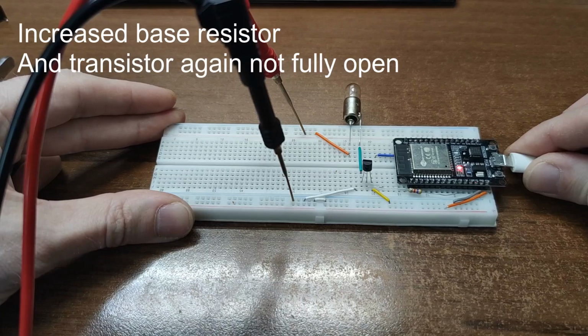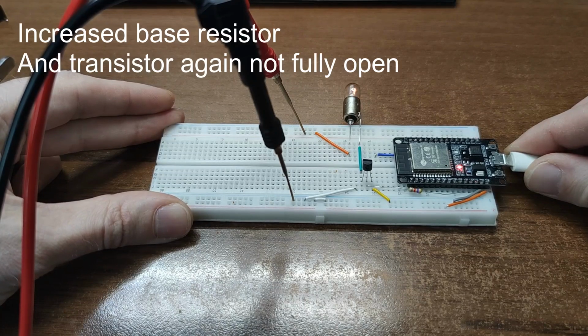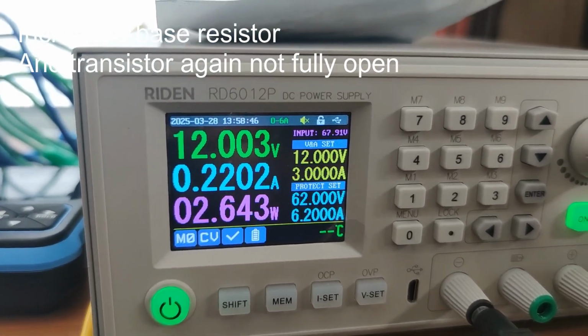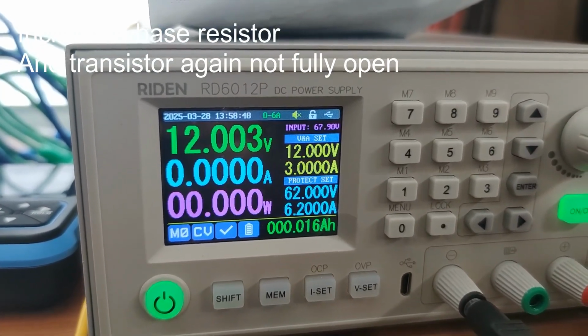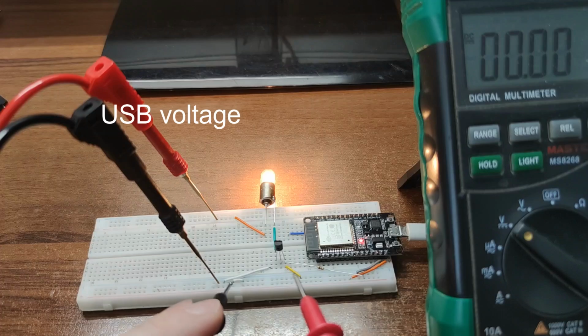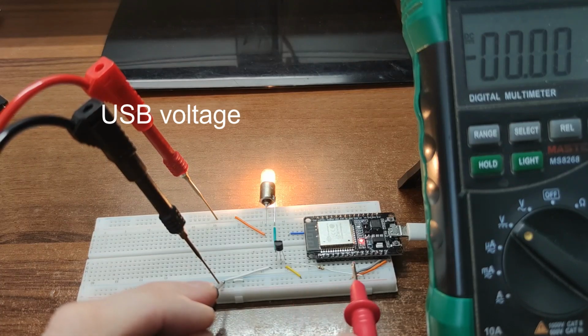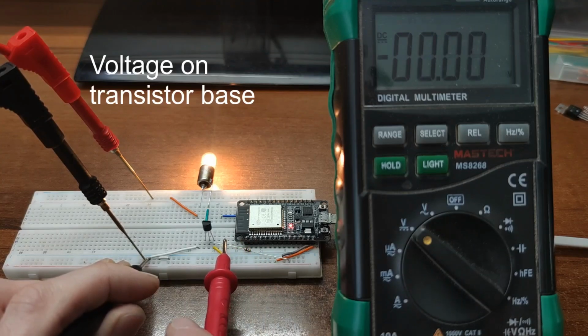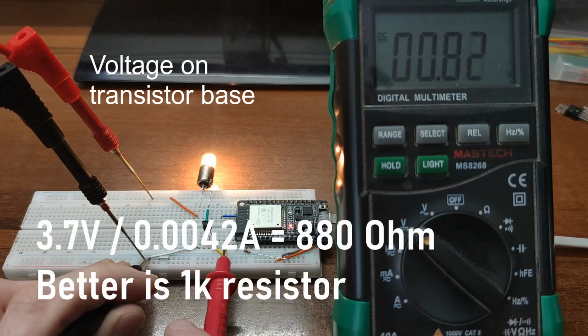I intentionally increased the base resistor value just for the experiment. And because the current ratio is fixed, both currents are decreased. Here I powered my circuit from a PC USB port. 4.5 volts is supplied, base is 0.8 volts, so it leaves 3.7 volts to the resistor. You can calculate desired resistors by dividing volts by amps.